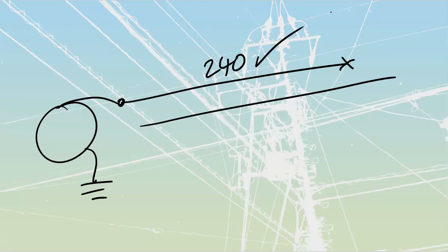This is not something that is going to be out of our Canadian Electrical Code. This is a requirement of the National Building Code of Canada. What we want to do is just make sure that nothing can spread through those. If we have got totally enclosed non-metallic raceways, like plastic conduits, PVC conduits, or anything like that, or if we've got conductors that are passing through, they also have to be rated according to the National Building Code of Canada. We're not allowed to just run Loomex through from one side to the other. We need to make sure that what we place through those won't burn away and allow that fire to cross through to the other side.